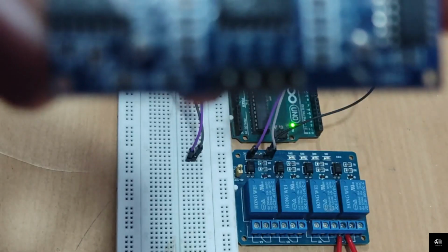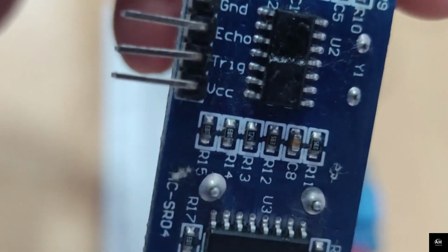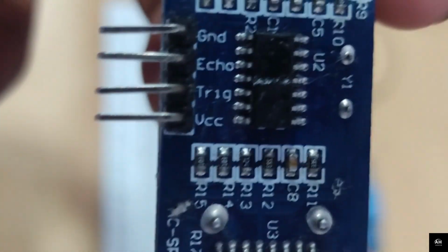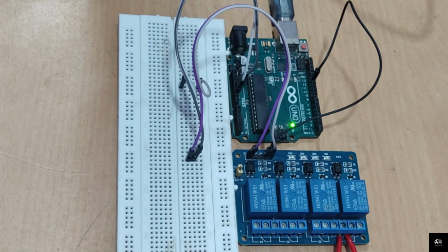So you can see on the screen that it has 4 pins. I will try to show you the pins. The first one is the ground, the second one is the echo, the third one is the trigger, and the last one is the 5 volt. So using the echo and trigger, it sends a sound wave and tries to measure the distance as it receives that data. Basically it will transmit a sound signal, and it will receive that sound signal, and according to the time it requires to get the signal back using the echo, it determines the distance to the object.